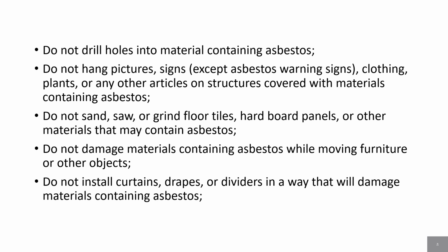Do not drill holes into material containing asbestos. Do not hang pictures, signs, except for asbestos warning signs, clothing, plants, or any other articles on structures covered with materials containing asbestos. Do not saw, sand, or grind floor tiles, hardboard panels, or other materials that may contain asbestos. Do not damage materials containing asbestos while moving furniture or other objects. Do not install curtains, drapes, or dividers in a way that will damage materials containing asbestos.